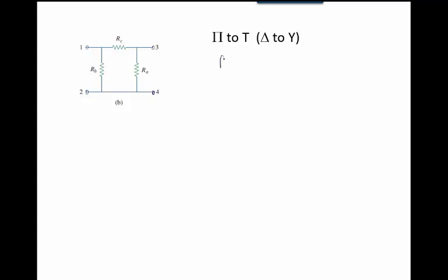So the resistance between 1 and 2, that's what's going to be between terminals 1 and 2. I see that these are in series. These are nothing. These are just like hanging out wires in the air right now. They're reference points. They're not anything. So if I were to see the resistance between there, I see these two are in series, and these series are in parallel with that one.